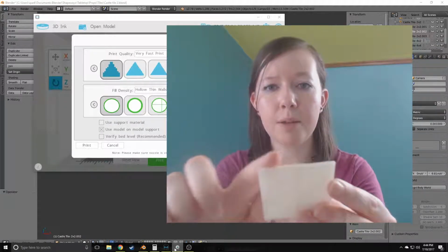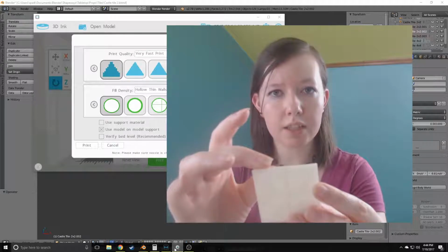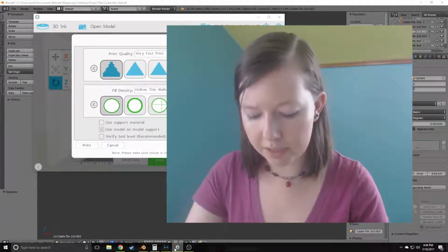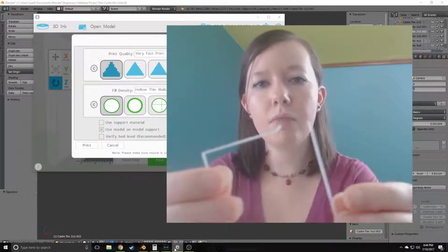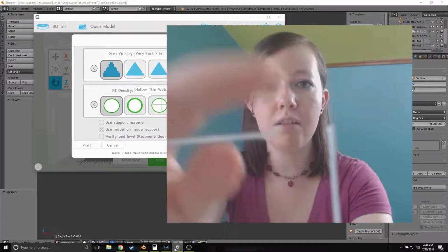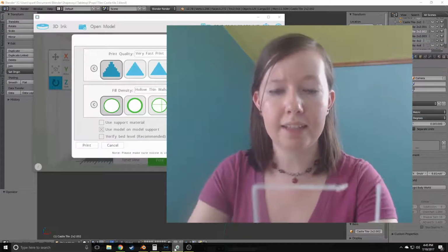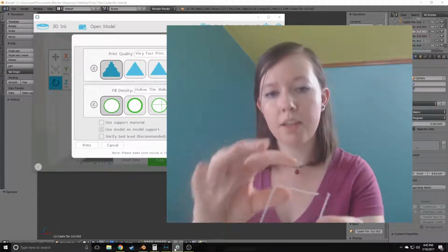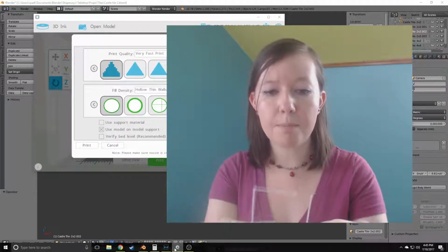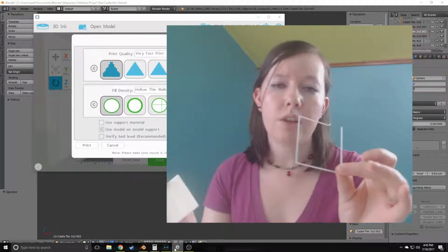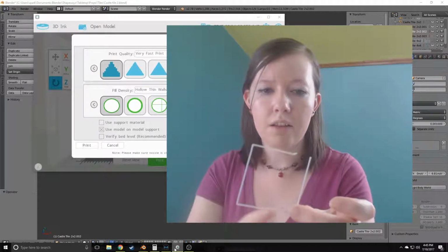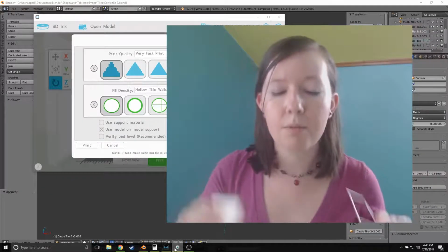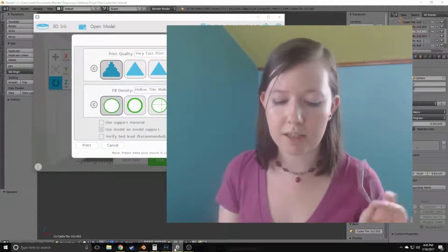So in order to make sure you don't get any extra plastic or clogs stuck onto the model, like with the skirt that printed with this tile, go ahead and print a skirt so that any clogs come out during this test square. It'll print essentially a ring around your print. It starts here and then starts printing the base inside of this. So I always recommend doing a skirt so you can get any clogs out. You find the issues here, then it'll do your model and you won't have any issues. Much better. Highly recommended to leave that on.